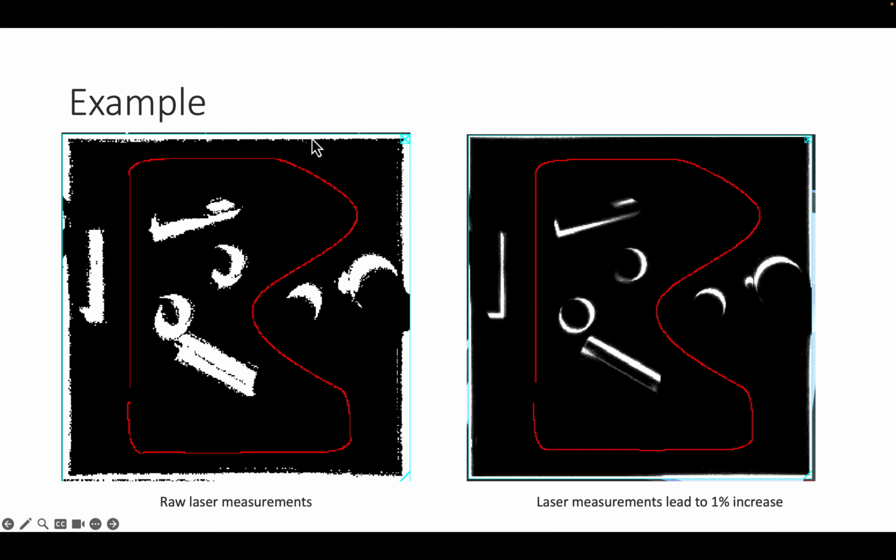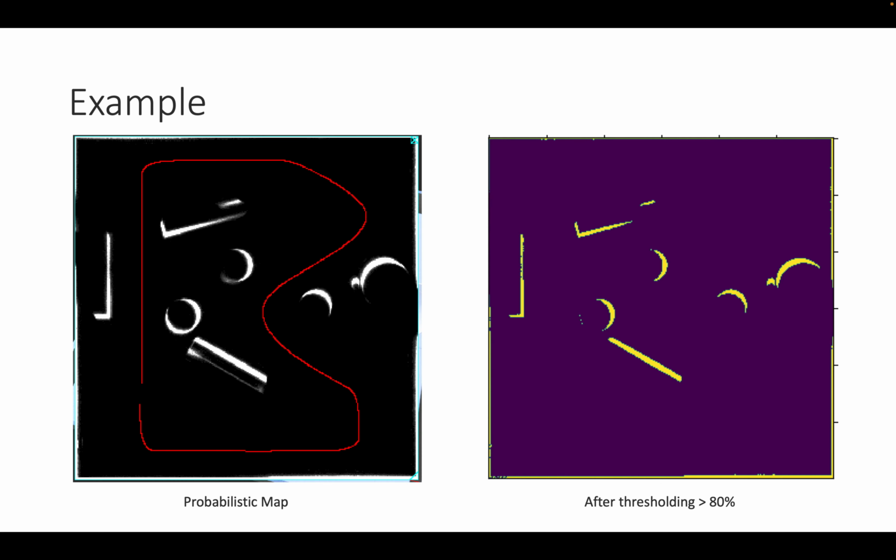you will see is all the spurious measurements here are gone, and I remain with very bright obstacles that I saw very often, and less bright ones as the robot hasn't seen these things more than, let's say, 50 times. I can then use this data and threshold it and say, okay, these are the obstacles that I will store on my map. And you see here, in this case, even this part of the circle has only been stored as 3 points because it hasn't been bright enough.